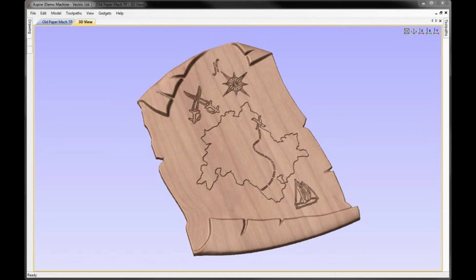In this tutorial, we're going to show you how to take the Parchment model that we created in one of the earlier videos and set it up to create efficient toolpaths so that we're not wasting too much time by machining flat areas using 3D finish strategies. To do that, we're going to create vector boundaries that limit the area that the 3D machining cuts, limit the area where we can pocket machine to clear away the main flat surface of the design, and we'll also show you how to add the decoration that you can see here as well, and ultimately cut this out.